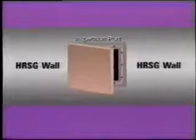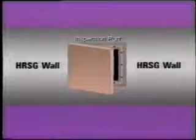Note on this arrangement that various inspection doors are provided so as to allow access into different areas of the HRSG. You must always make sure that the access doors are well sealed so as to prevent leakage. Remember, the gas inside the HRSG is under a positive pressure, and any leakage to atmosphere will result in a heat loss. In some units, a seal air system is employed.